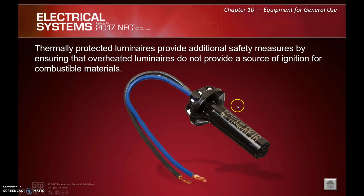Furthermore, if you've ever seen a device like this and wondered, maybe you don't know what it is, maybe you do. It's actually a thermal protector for a light fixture. So what will happen is, if that thing gets hot, we run our circuit through these wire leads here, and it will actually open up, breaking the connection and shutting the light off. Once it cools down, it'll close again and relight the light.